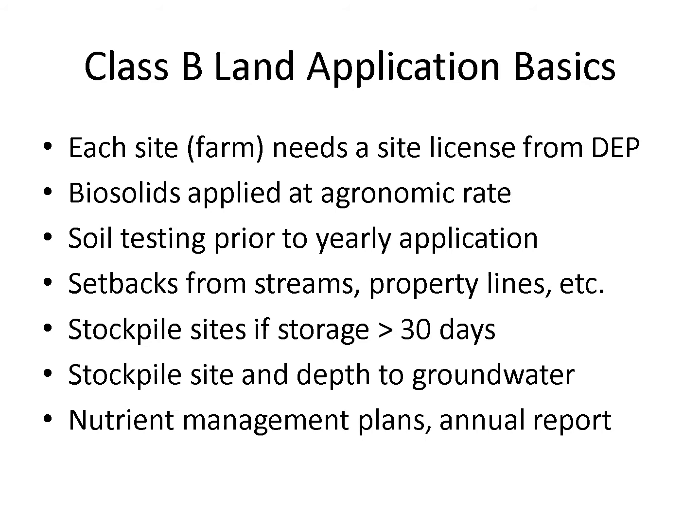Soil tests have to be done yearly, and account has to be made of any residual nitrogen from application of previous years. There are setbacks that we'll look at a little bit more from streams and property lines and so forth. If you're going to stockpile biosolids for longer than 30 days, which is particularly important for a smaller facility, then you need to have a specifically permitted stockpile site on a given farm field.